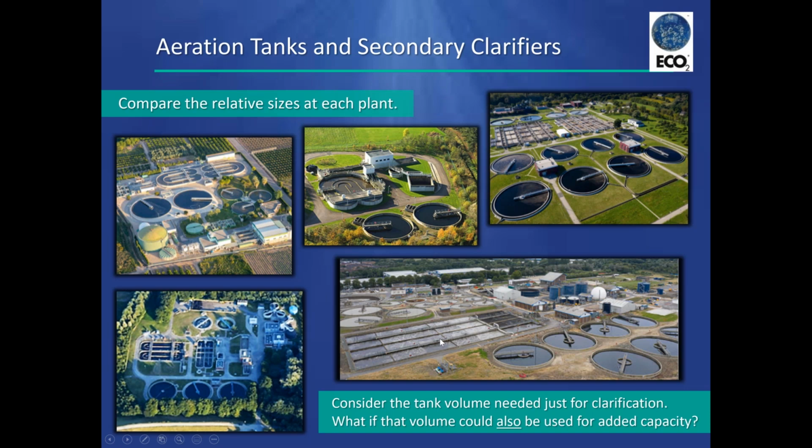So the characteristic is aeration tanks, lots of turbulence, clarifiers have to be something that's very quiescent. And so after the aeration tank, following these very turbulent conditions, we then go to a very quiescent condition, and in that quiescent condition, the bacteria are able to settle out.